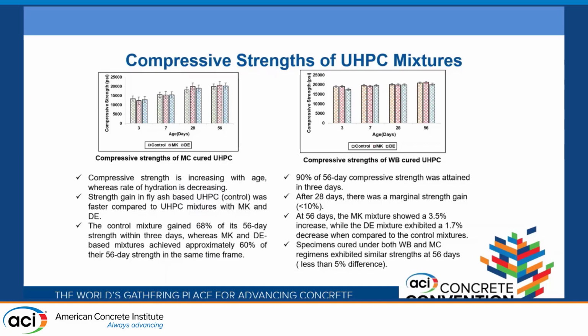The strength gain in the control mixture was faster than in the modified UHPC mixtures. At 7 days, the compressive strength in all three mixtures showed similar results, and there was a substantial increase in the compressive strength from 7 days to 28 days in moist curing condition.